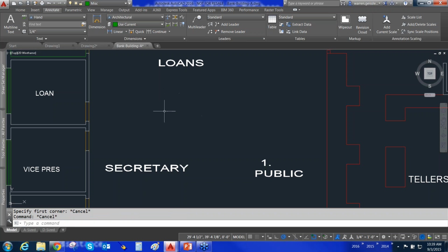Warren, how did you change that? Well, here's how you change that. There's a little known command inside of AutoCAD called MT jig string. Look down there at the bottom of my screen. I just started typing in MTJ and the autocomplete filled it in for me. This tool has been around for a number of years. You type in MT jig string and you get to edit your jig string. That's what a jig string is. It's a string that pops up there in front of you, and you can type in anything you want, up to 10 characters. So don't get too carried away.